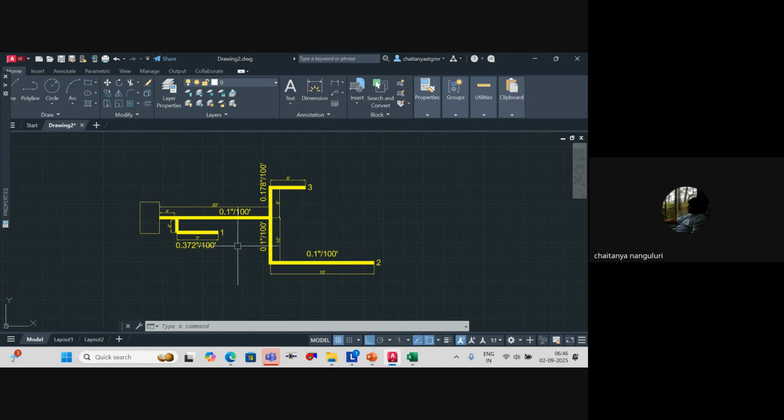Whether it is the path from the AHU to path 1, path 2 or path 3, my total friction factor is the same, so the resistance offered is the same. Do you think your airflow volume will be distributed equally? Yes or no? Yeah.